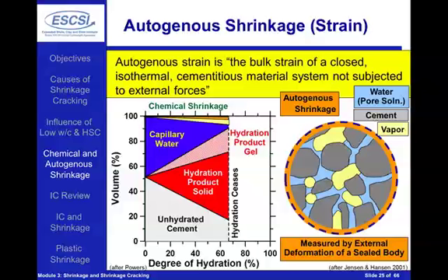Now, it's important to understand that this concept of vapor-filled spaces forming happens in every single concrete every single day, unless there's an infinite amount of water being placed at the surface of the concrete. However, these vapor-filled spaces become very, very important in lower water to cement ratio systems, mainly because of the size of the pores that these vapor-filled spaces can form in. If they form in large pores, generally they don't result in the development of a lot of stress. Therefore, you don't see a lot of external volume change.